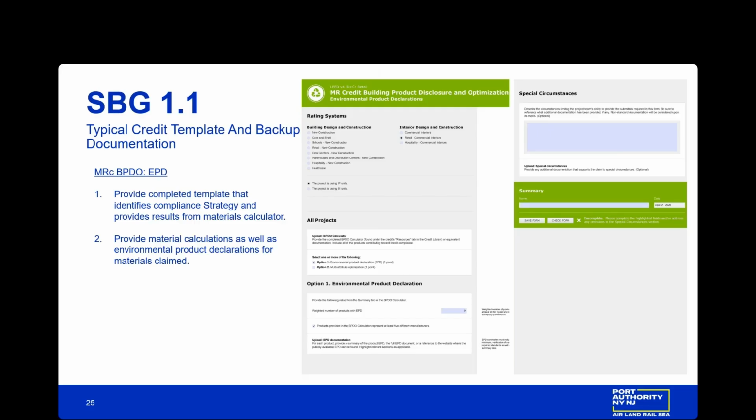Now, for a typical LEED submission in 4.0, this credit required a very onerous 20 materials from 5 different manufacturers. This made it one of the least sought after credits. At 4.1, they reduced that to 10 materials.